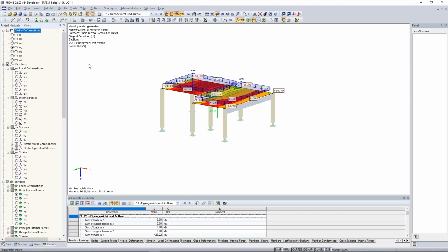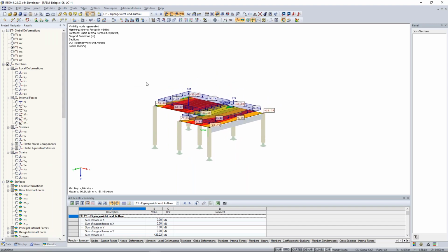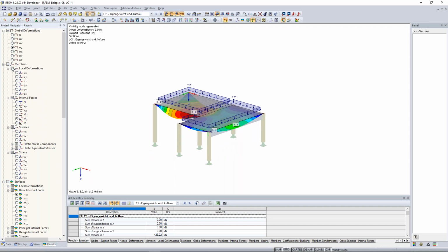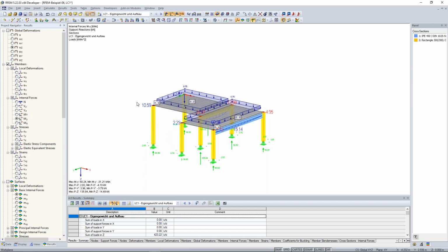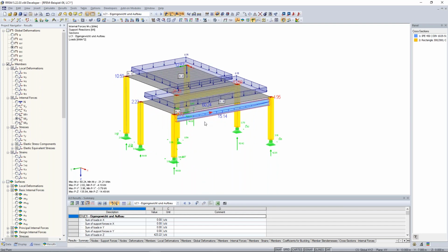Okay, now to the fourth tab and the last tab of the navigator. Here I can show the results. First of all, maybe the deformation. I can show here the deformation under global deformation, but also maybe some internal forces. So when I cancel the visibility mode that I have done before, I can show maybe the bending moment. So I just click here on M epsilon, and I see here at the downstem beam we have a nice field moment.